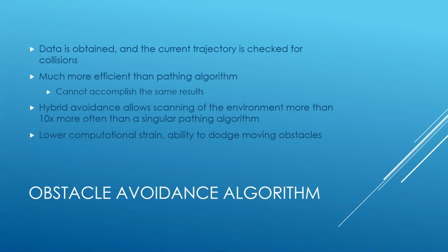As the drone travels, it can account for these changes by continuously collecting data and checking for immediate collisions of the drone along the current path. If any obstacle is detected in this way, the UAV must affect its movement such that the collision will no longer occur. If it moves in this way, the navigation process must repeat, such that the path can be recalculated.